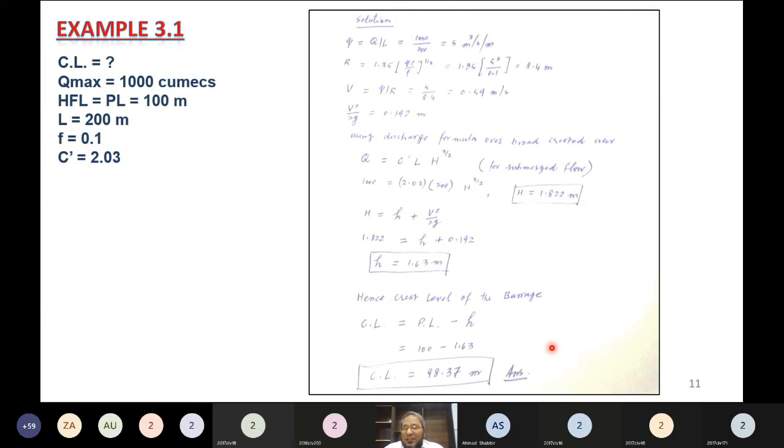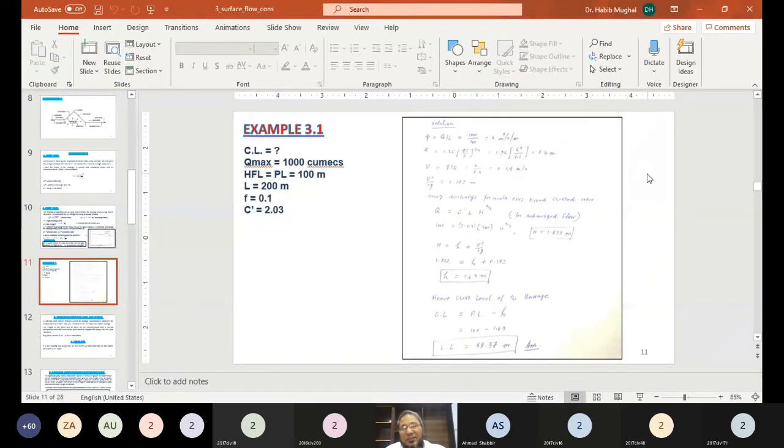Yes sir, that we have studied in the hydraulic engineering subject very clearly. If we provide a hump, what change comes in the water surface profile? Only locally the water surface profile goes down. Right? Yes, sir. If the flow is subcritical, then no damming action takes place. No efflux takes place on the upstream side. But when the hump height is greater than the critical hump height, then efflux or damming action takes place on the upstream side. So I think we should stop here because you might have the next lectures, and inshallah we will continue this chapter. It is a very interesting chapter relating to the design of the barrage.